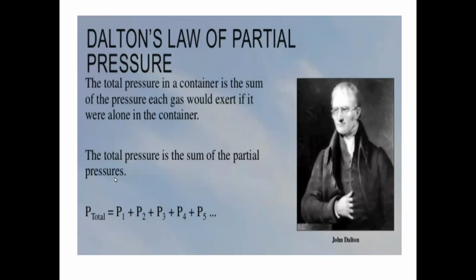Like if we say about the condenser, in the condenser there is steam coming from the turbine. Okay, and along with that steam, some air also enters into the condenser shell. So what is in the condenser shell? That is the mixture of steam and air. So as per the condenser theory, the total pressure inside the condenser shell is equal to the sum of the steam pressure plus the air pressure. So that is the total pressure inside the condenser shell.